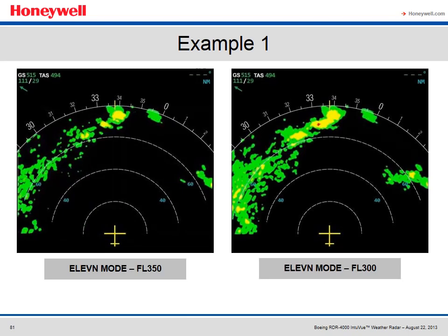But analysis using constant altitude slices indicates the bulk of the reflectivity from this feature is not seen until about flight level 300, which reduces the threat level somewhat. Given the wind direction of right to left, the pilot should be planning a deviation to the right side of the two cells, which makes any reflectivity to the left of no interest.